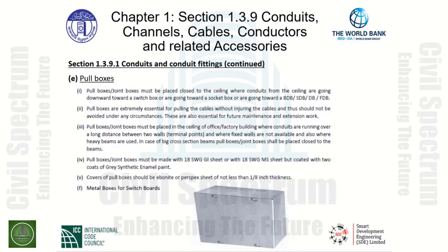Again, we want to make sure that the durability of these pull boxes stays intact for many, many years. Item number 5. Covers of pull boxes should be ebonite or perspex sheet of not less than 1/8 inch thickness. Item F. Metal boxes for switchboards.